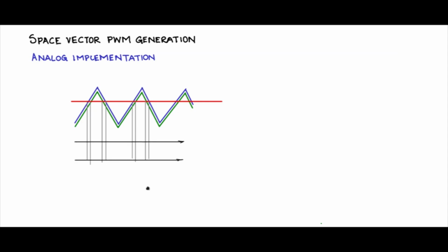And let me have two axes, both are time axes. Let's say one is representing the top switch and the other is representing the bottom switch of one arm of an inverter. So let us say this is the A arm of the inverter. For the top switch I will use a comparator, plus and minus like this. I will give Vc to the positive pin, and to the negative pin I will give the blue triangular carrier in this fashion.